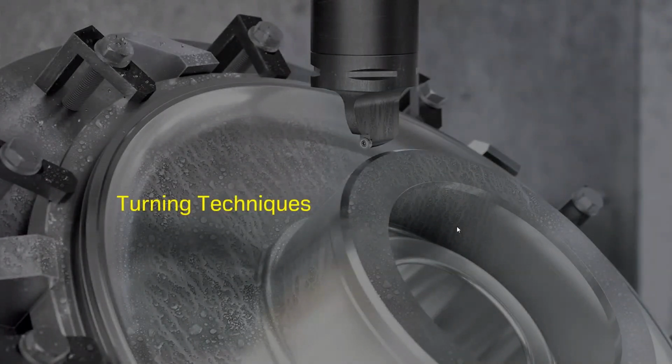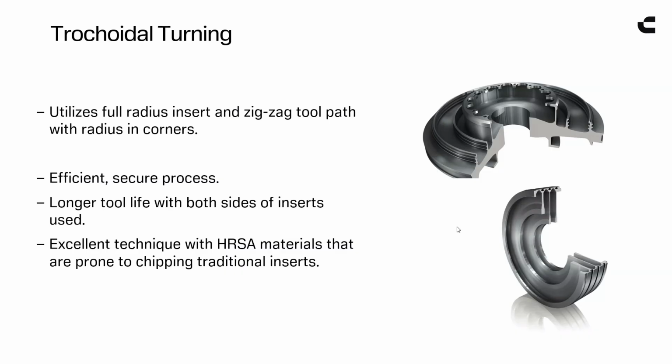Okay. So we talked a little bit about a grade example, a little bit about some of the SL70 holder examples, which are fantastic. But now we need to talk about the turning techniques to use. It's not just enough to use the correct insert with the correct holder in a multitask machine, but you want to utilize a good technique. One of those techniques is called trochoidal turning.